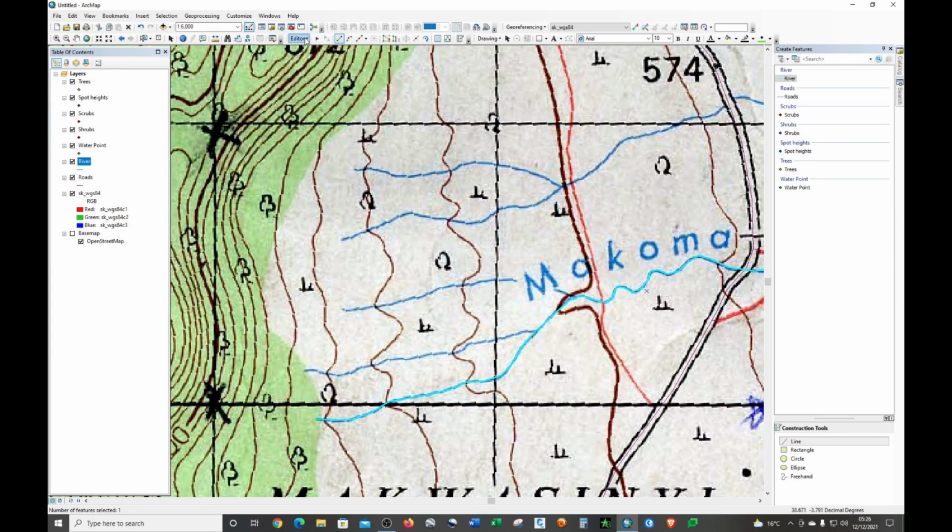And I repeat again, if you want to switch on the snapping tool, just click on this Editor, then Snapping, then Snapping Toolbar. Make sure that you check all these options. You have edge snapping, vertex snapping. This one actually snaps the edge. This one vertex, and end of a feature. This one is point snapping.